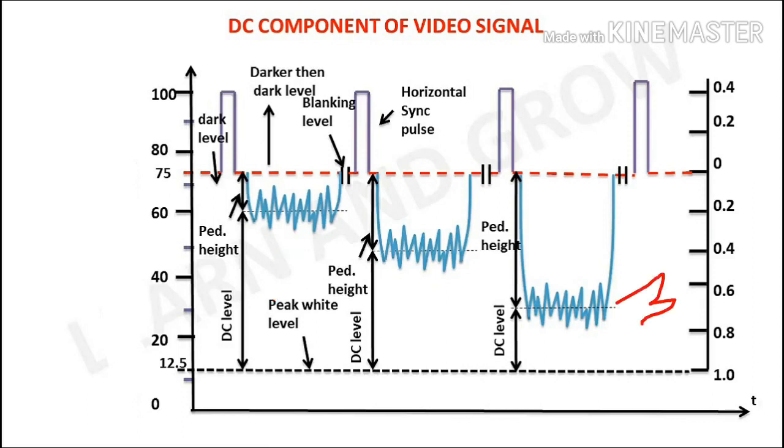The vertical blanking period begins with a group of 6 equalizing pulses, spaced at half-line intervals. Next is a jagged vertical alignment pulse that actually produces a vertical flyback in the scanning circuit. Serrations also occur at half-line intervals. Thus, a complete vertical alignment pulse is 3 lines wide. Following the vertical alignment is another group consisting of 6 equalization pulses and a series of horizontal pulses.